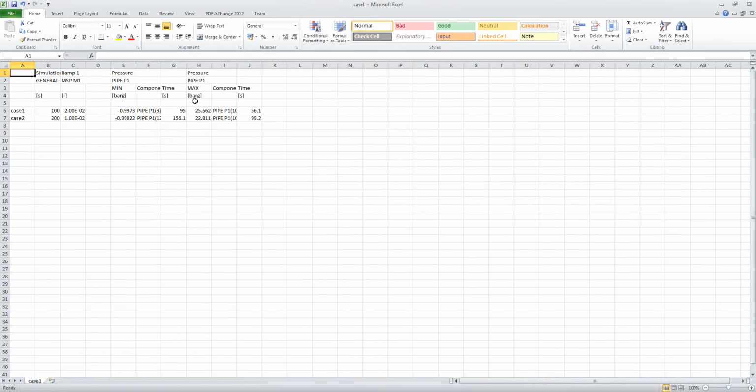And it's finished. And then you get this Excel opened with the outputs, and here we can see the inputs which I've given in here, the extreme pressures. And for example, you can see that for the 50 seconds closure time, the pressure is higher than for the 100 seconds, that is as expected. But still in both cases we see cavitation occurring.